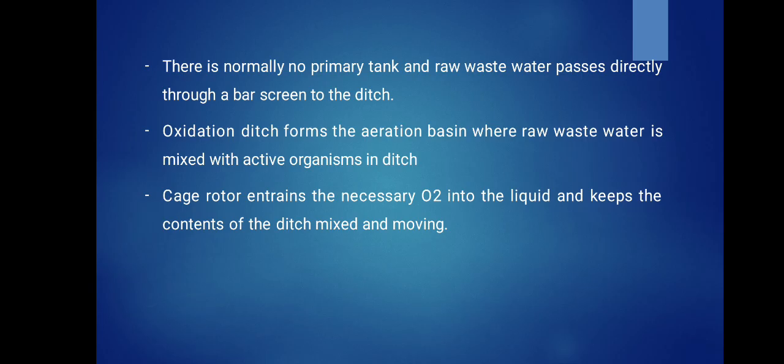Here there is no primary tank. Directly the wastewater gets poured into the ditch. Just one filter or a bar screen is present to filter the floating particles present in the wastewater, at the inlet. Then the raw water is directly passed into the oxidation ditch.